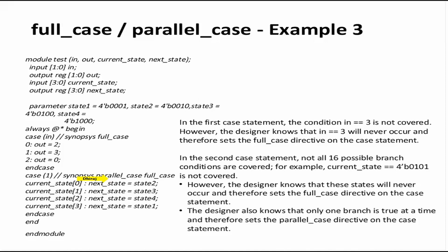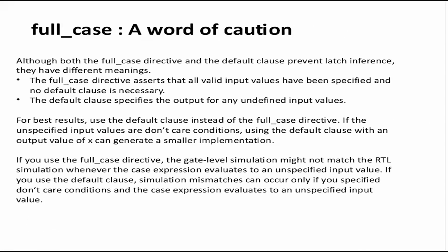If you're not confident, if there is even a 1% chance that these cases can occur, then please make sure that by design your case block should be full and parallel, and there should not be any need to use the full case and parallel. So a final word of caution. Although the full case directive and both full case and default clauses prevent latch inference, they have different meanings.